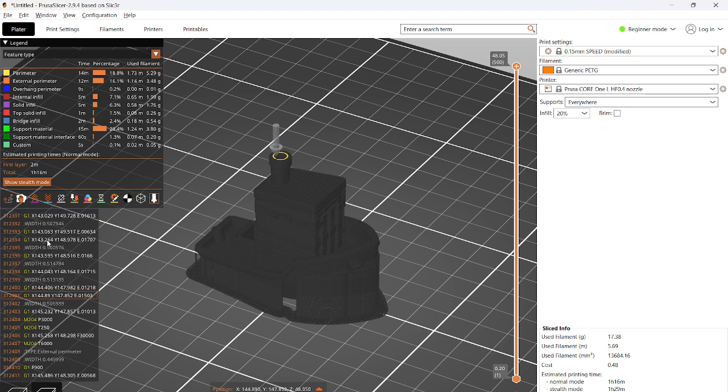And if you look, there are very, very small incremental changes. It's like 143.063, and then the next command is 143.264. So these commands are very close together. These G-code files are typically thousands or maybe even millions of lines long, and they're all movement commands or small macro commands. If you are super nerdy like I am, you can read these, which is kind of sad, but I guess I can read them now.